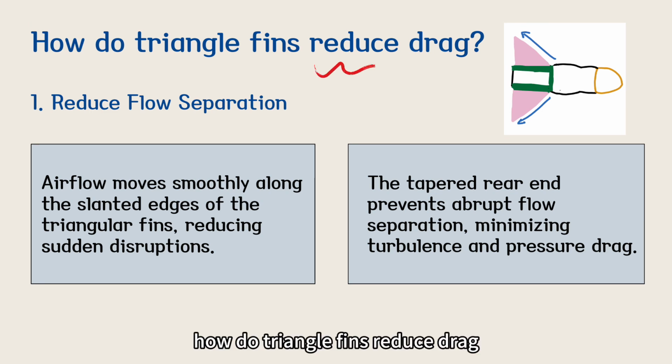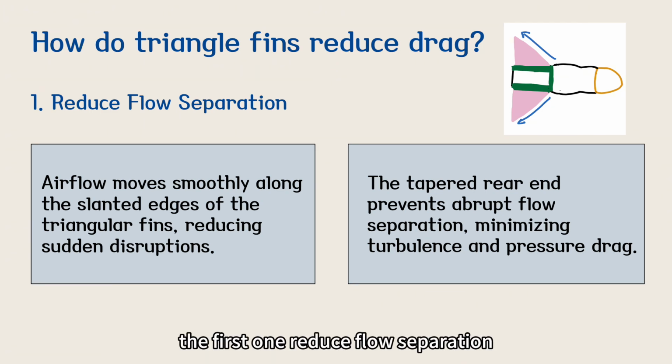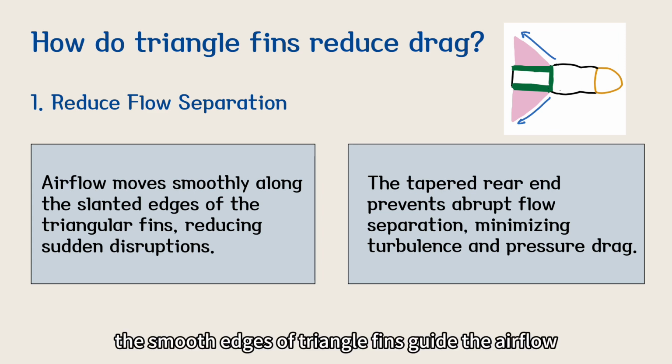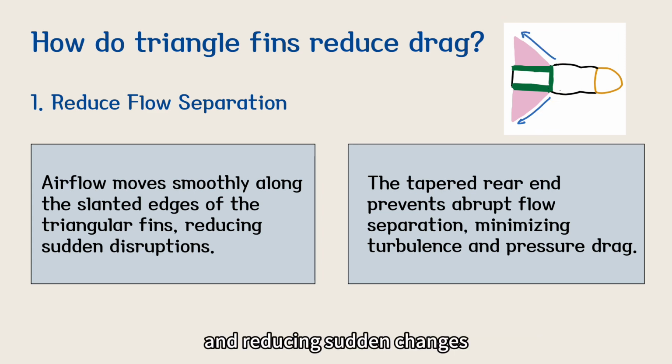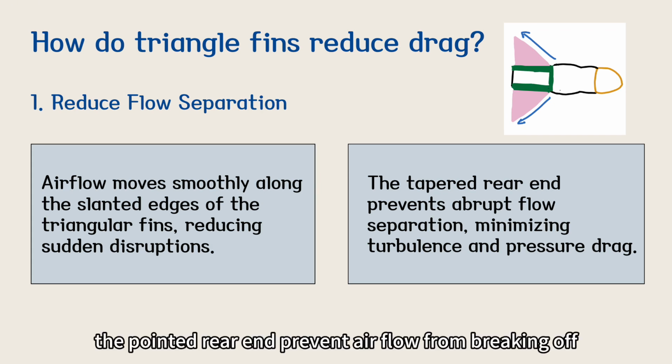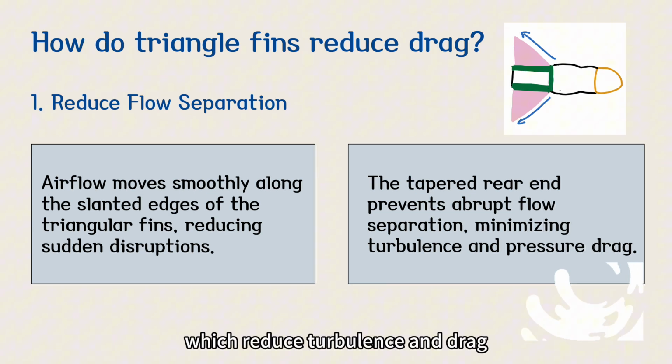How do triangle fins reduce drag? The first one, reduce flow separation. The smooth edges of triangle fins guide the airflow and reduce sudden changes. The pointy rear end prevents airflow from breaking off, which reduces turbulence and drag.